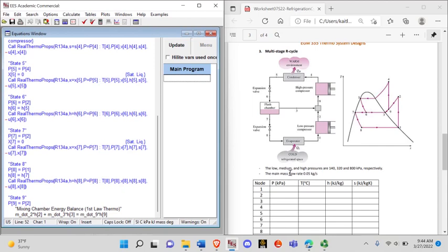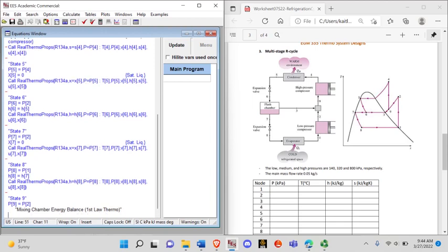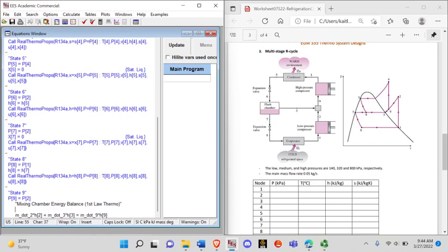And here it says the main mass flow rate is 0.05 kilograms per second. I'm going to assume that the main mass flow rate is state 9, but I would ask your professor what the main mass flow rate is supposed to be. So I'm going to put here m dot 9 equals 0.05 kilograms per second. So the only knowns we have are H2, H3, and m dot 9. Our unknowns right now are m dot 2, m dot 3, and H9. And H9 is what we need to find, so we get another thermophysical property value at state 9. So we need to manipulate this equation to find m dot 2 and m dot 3.